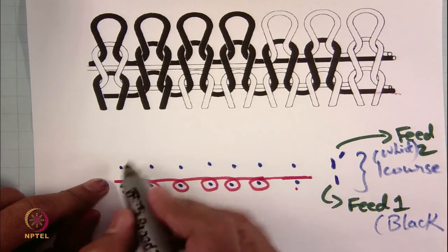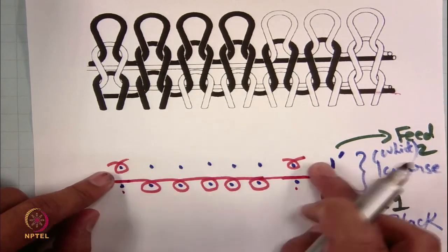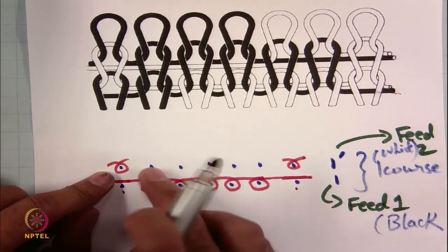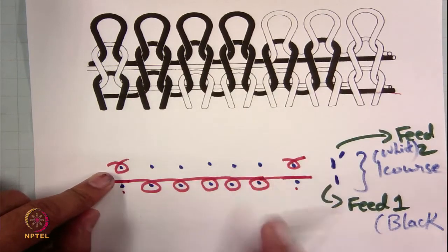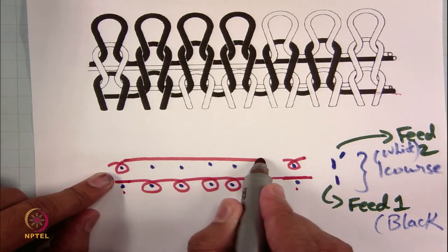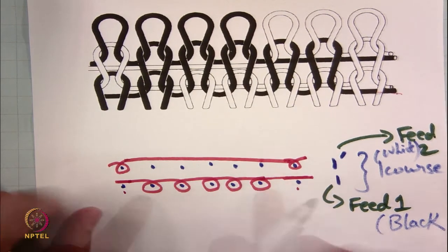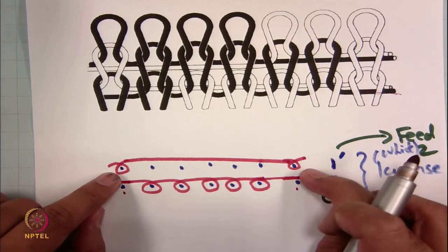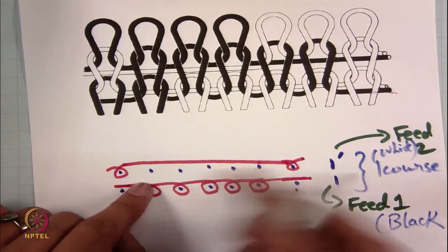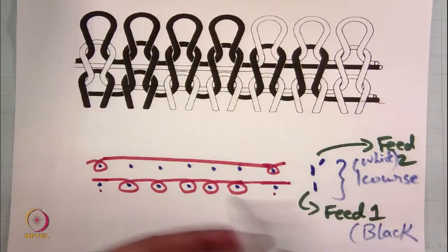So, we are actually making a white loop in the second feed in the first course, and the next 5 needles which were making loops with the black yarn are not doing anything with the white yarn. That is why this is float. Okay. So, black yarn is operating 5 needles, the other needles are not working. When other needles are working, then these 5 needles are not working. So, alternately, it is basically selection of long butt needles and short butt needles. This is for the first course.